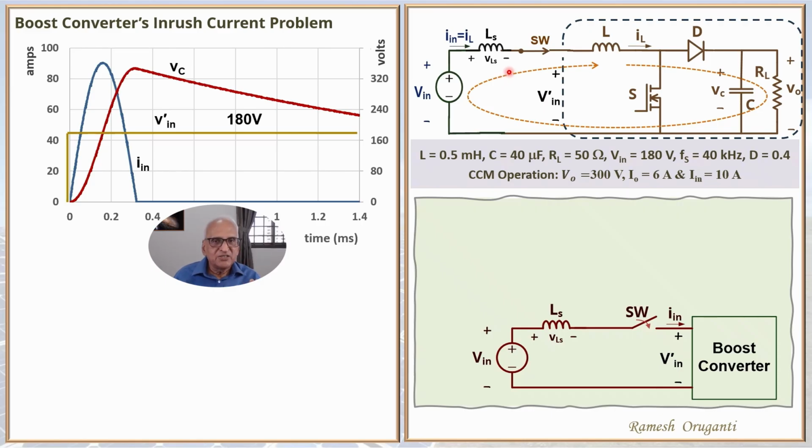You have to deal with this on a case by case basis, but in general, V dashed in is unlikely to change much due to the presence of the wire inductance. There is yet another reason. This V in may be a power electronic source itself. This power supply V in has some characteristics. As you load it with some current, the voltage remains constant at V in. That is the definition of a voltage source.